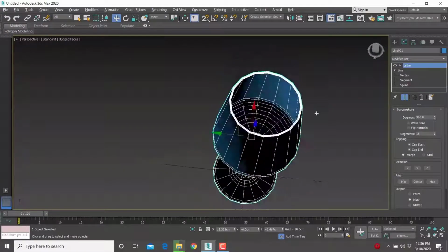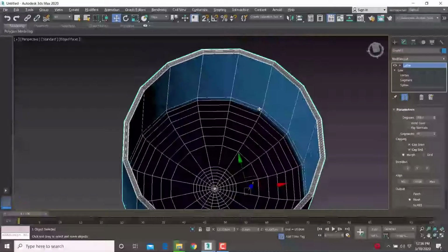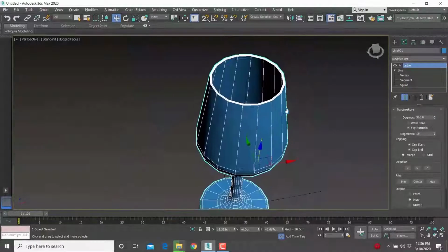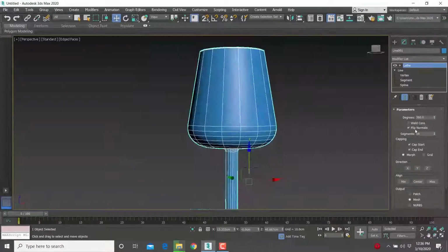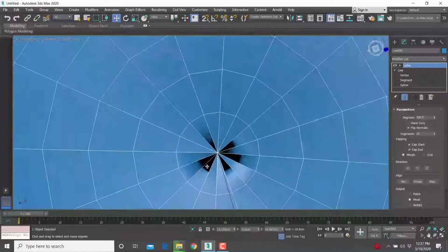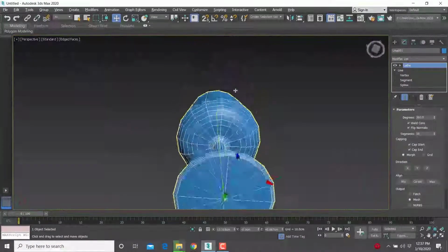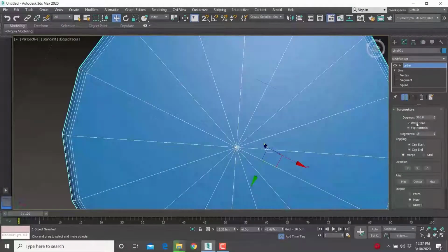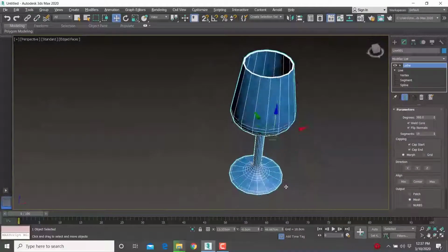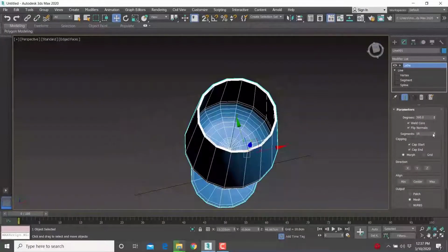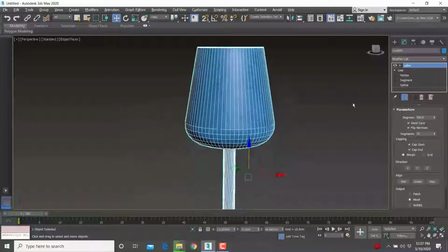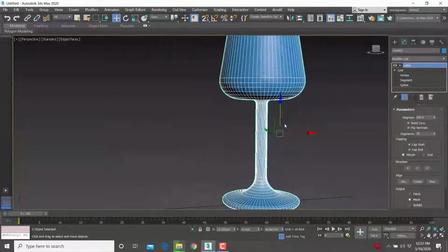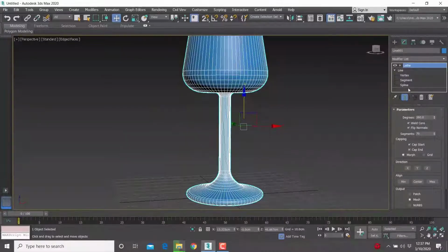Now, I think this is going the opposite way. Okay, I can flip normals, so I can flip the faces from being inwards to go outwards. I can also weld cores, which is here, and the core in here, which is where it is revolving. Okay, and now this is what I want. Another thing I can add is basically the segments to make it more smooth. Okay, and done. Voila.